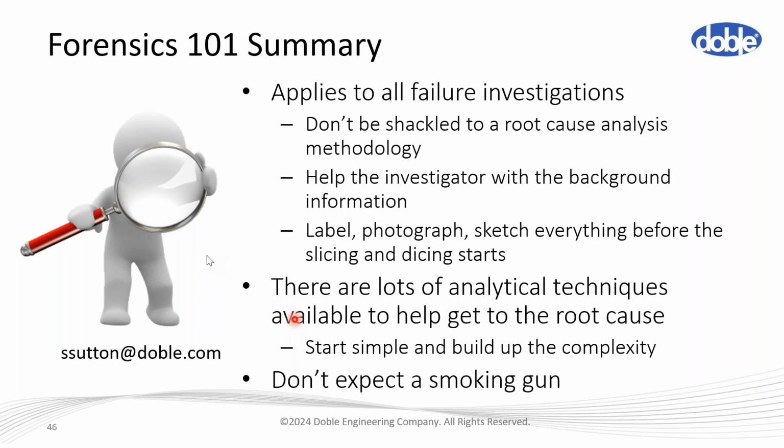If it's an XLPE cable, and depending on if you think it could suffer from water treeing, people will do VLF tan delta to detect water trees. That's normally for medium voltage cables that don't have a metallic sheath. And then if it does have a metallic sheath, and even if it doesn't, partial discharge testing is probably as good a method as we get these days.